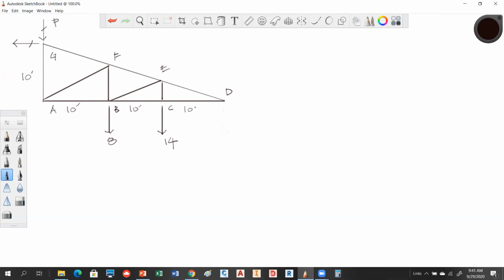That's going to be RGV, right? And this will be RGH, correct? And what about that roller? Which way is he reacting? Left, right, up, down? Is he this way or is he vertical? Wouldn't it be horizontal? It would be, because notice that the surface over which it's rolling is a vertical surface.